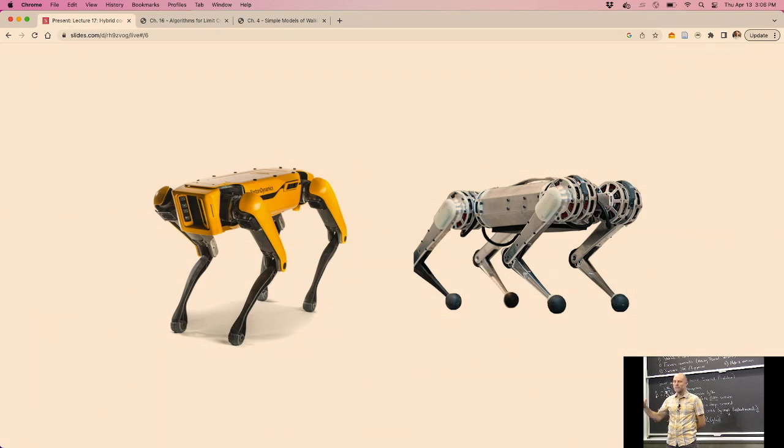I think there's regimes where locomotion should be easy, right? This is highlighting it. I do think there's gaps. I think real actuators don't do instantaneous leg angles and stuff like this. But in that sweet spot, I think control does become easy. In fact, there's different mechanisms for stability in a legged robot. One of them, of course, is regulating angular momentum and regulating your torso and things like this. But foot placement, your choice of foot placement, is a dominant mode of stabilization. And I think that's really what happened. A lot of these robots got to the point where they could move their legs so fast that they could place their foot arbitrarily, and that makes locomotion a lot easier.